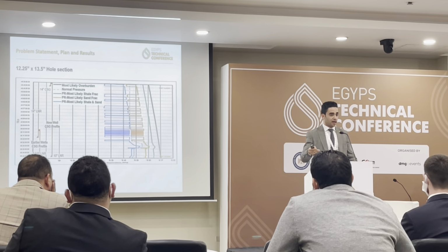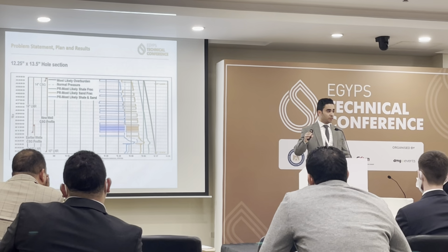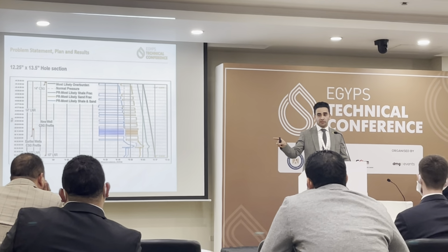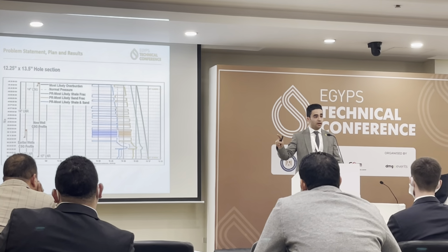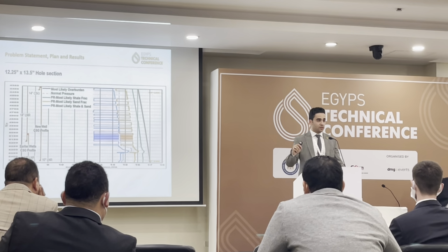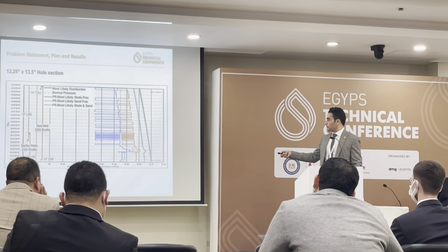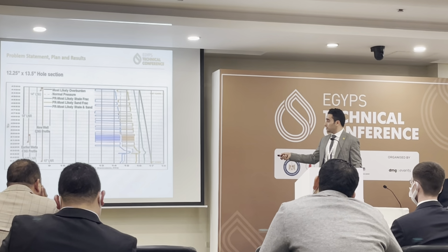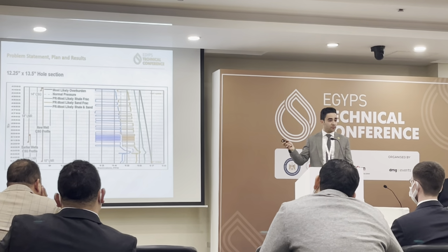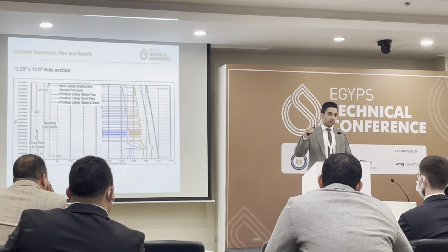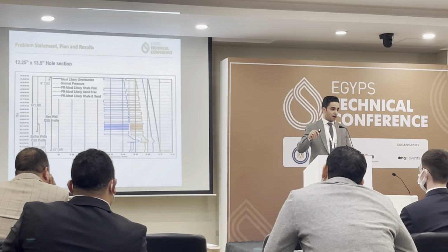slight background that actually kicked up to 50% of the gas. So we stopped drilling, we diverted the flow to the mud gas separator, and circulated until we reached the 5 to 7. And then at the depth of 5,633, we got losses of 70 barrels per hour.